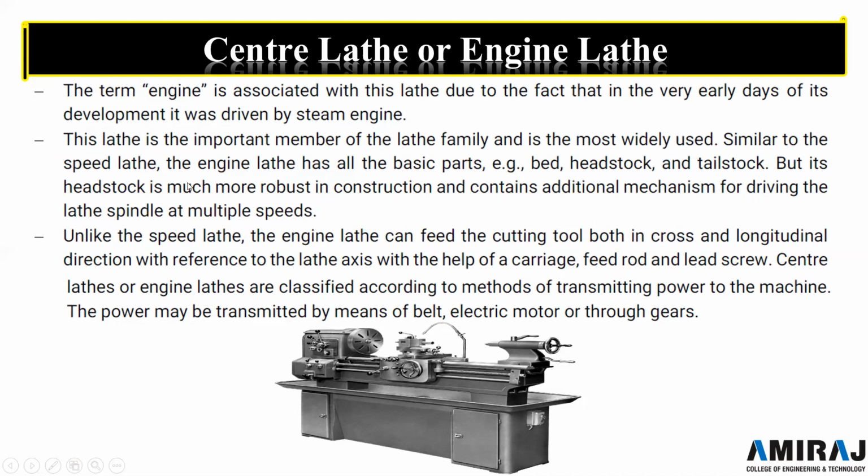Similar to the speed lathe, the engine lathe has all the basic parts like bed, headstock, tailstock, but its headstock is much more robust in construction and contains an additional mechanism for driving the lathe spindle at multiple speeds. So here there is an arrangement in the headstock, an additional mechanism, so that we can change the spindle speed.